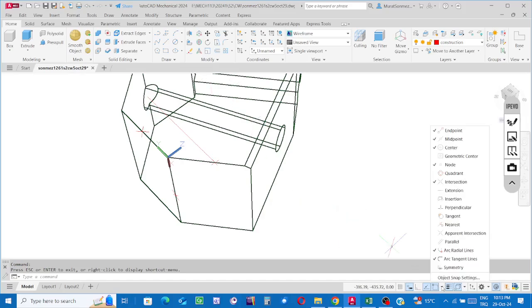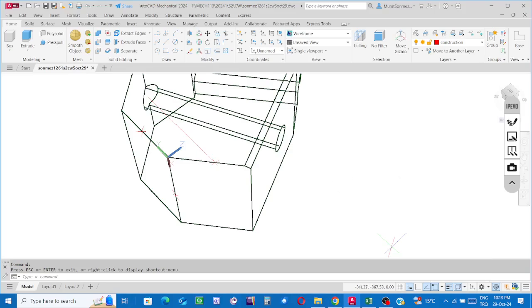The point node option is selected. It is to enable nodes to snap the cursor. So everything is okay. Can start the polyline process, 3D polyline. And then indicate this point, while seeing the highlighted symbol, indicate this point.